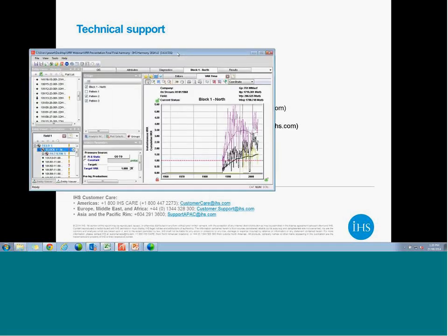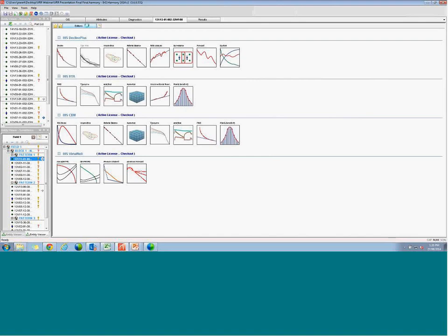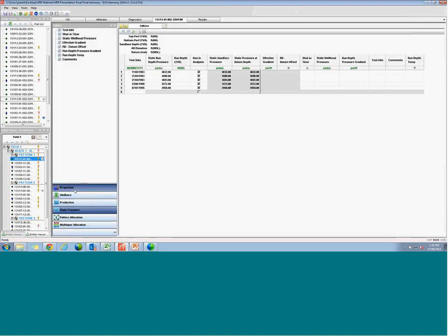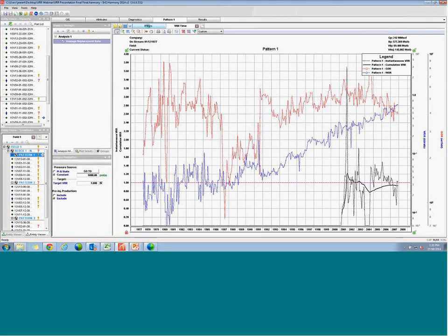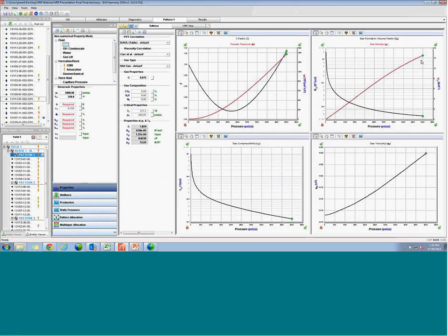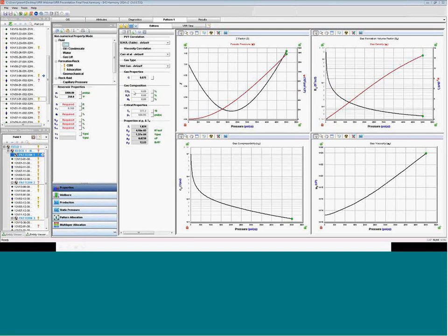That's a really good question, because I'm not sure how permitting is done around the world, but what the PVT data is going to give you is a scope of what you used to actually generate your formation volume factors, which then led to your calculation of VRR. And so what we can do, properties, actually maybe I'll do it up here at the pattern level. Yes, we can. These were from correlations from just entering our initial pressure and reservoir temperature.